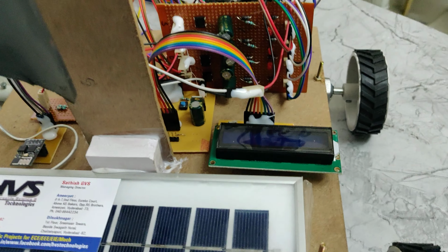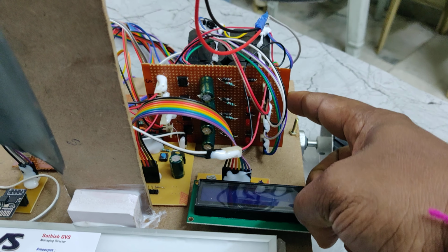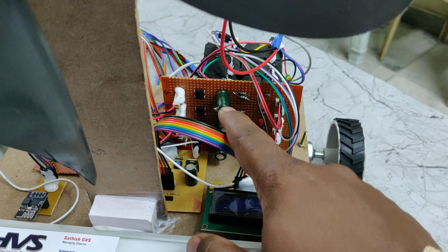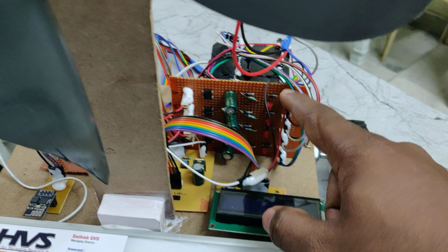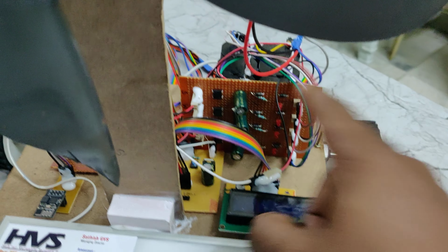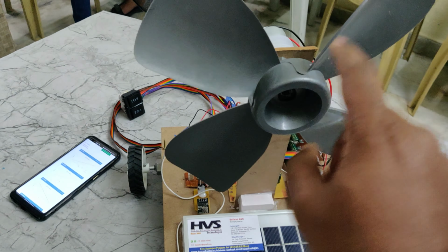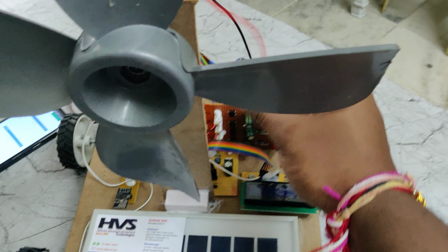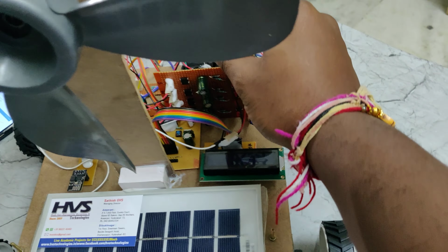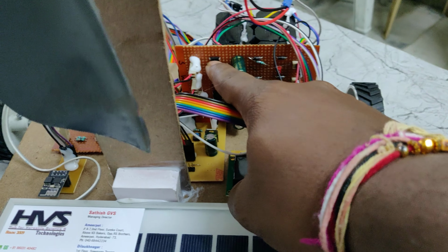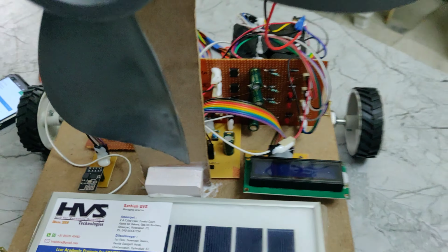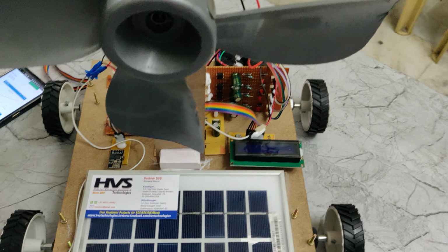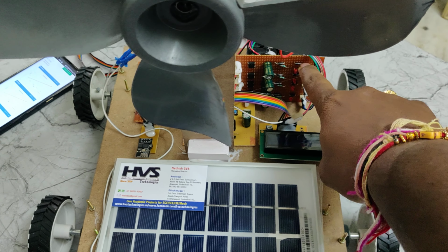It has 4 charging circuits along with rectifier, filter and unidirectional diodes. The rectifier's purpose is that if the wind rotates clockwise or counterclockwise, the polarity varies on the dynamo cables, and that will be rectified with the help of this rectifier IC. The filter is just to make the high current while charging the battery. And for unidirectional current flow, we are using 2 diodes.